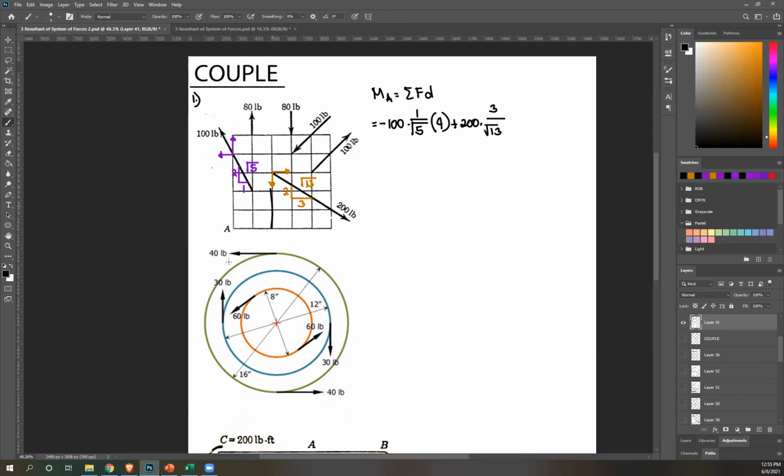Next, the vertical component, rotate about A. That's clockwise again, so plus 200. Sorry, forgot the distance. Don't forget the distance for a moment. Okay, distance of the horizontal side, so extend that. That distance is equal to 3, so times 3. Okay. Next, once again, vertical side, rotate. That's clockwise, so positive 200. Get the vertical component, so times the vertical side, 2 over hypotenuse, square root of 13, times distance. Distance of this is equal to this, so 2 units, so times 2.